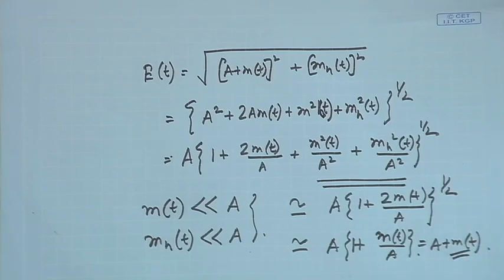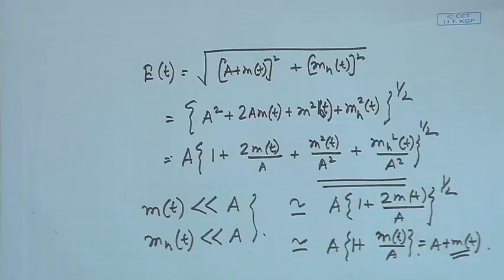So the condition is in SSB also like AM. See, DSB had a version AM where I was adding carrier, right, and with carrier I was able to do my receiving in a very simple way. What I was doing, I was just putting envelope detector followed by a DC blocker. Same thing I can do over here, but there is a condition.